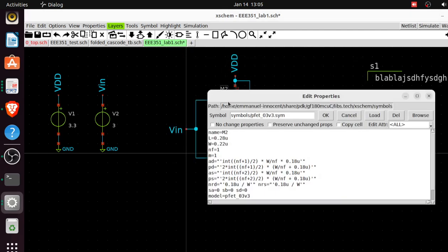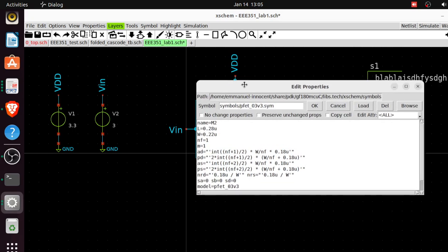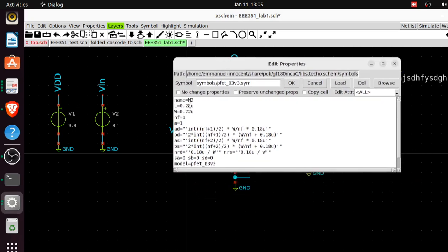Then I'll come to the PMOS. Like I said, we want them to have the same length. We're not varying the length. We're trying to be strict with the length, as in the process node. Let's just assume we want the length to be fixed. Then that's 0.3 micron or 300 nanometer.